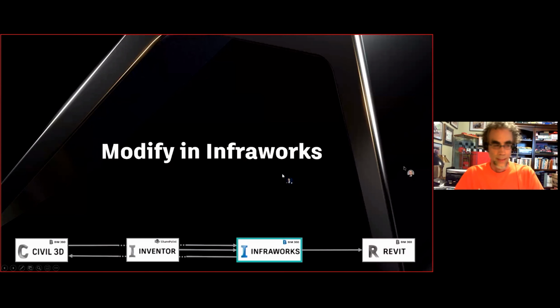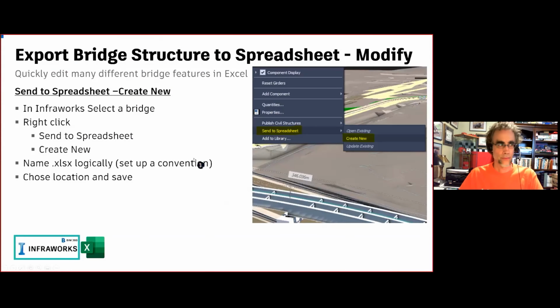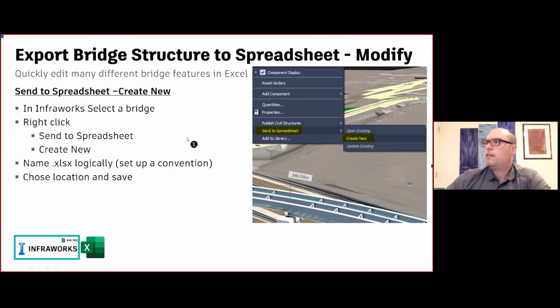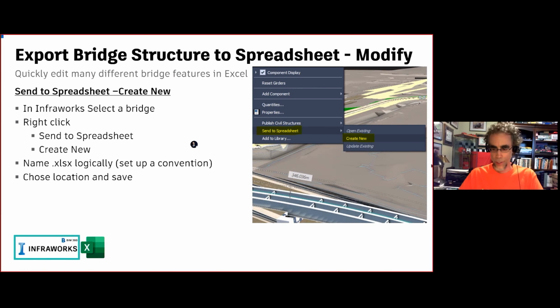Yeah, thanks, Danny. That's part of the cool part about this whole thing, and the parts that come out of Inventor and into InfraWorks. All the parameters in Inventor come into InfraWorks, and you could change them there and adjust the piece, and let InfraWorks adjust the piece as the girders move up, down, left, right, the spacing of them. Those pieces will flex with everything. They'll adapt, which is really important.